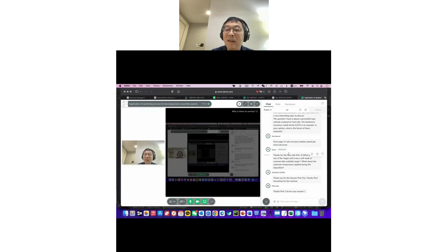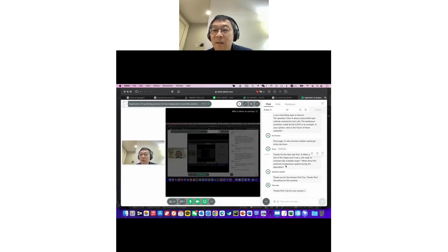We order the target from a good source, so-called high quality target. And the substrate temperature is typically something like 500 Celsius, because that helps, especially for structures like perovskite. It really helps to maintain the crystallinity when you apply typically about 400 or 500 Celsius for the substrate temperature. I think that may answer all the questions.